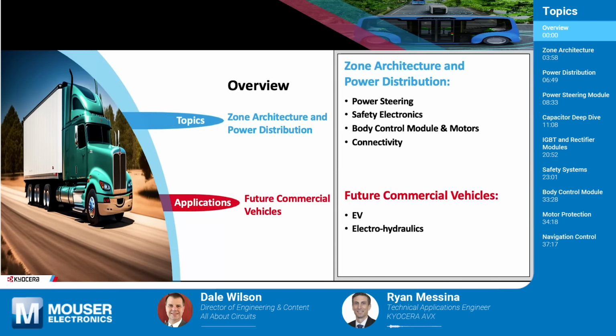There are several advantages that can be realized with zonal architecture. The first is that ECUs get more processing capable because you're breaking up each zone of the vehicle and they have their own dedicated ECU or zone module. You can use that interchangeably. Your zone module will be your ECU, and they can handle the tasks at those specific zones in real time, right away. So you don't have to have that latency or that length of signal lines and the delays that come with that long travel distance.